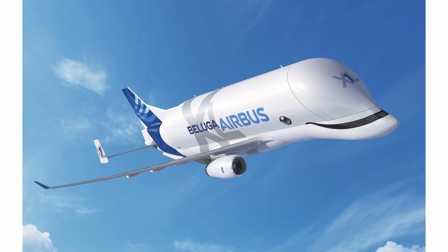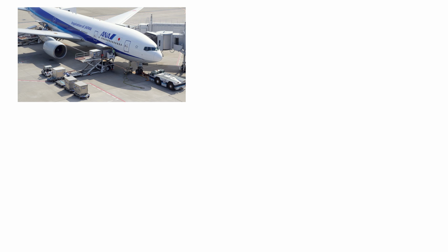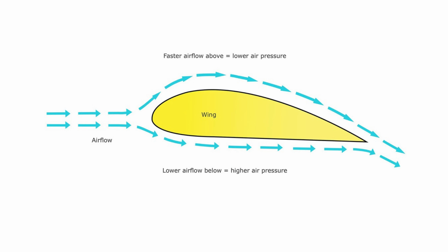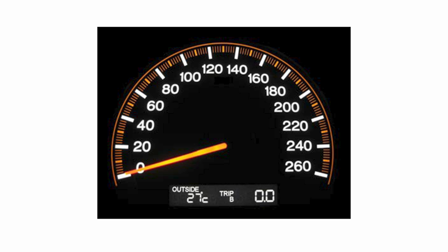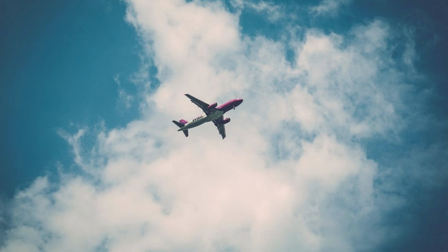Larger wings can generate more lift, which is why cargo planes and gliders often have wider wings compared to fighter jets. Engineers carefully balance wing size and shape based on the airplane's purpose, whether it's for carrying heavy loads, achieving high speeds, or maximizing efficiency. To summarize, lift is the result of a combination of factors: the airfoil shape, angle of attack, speed, and wing surface area. Together, these elements allow airplanes to overcome gravity and stay airborne.